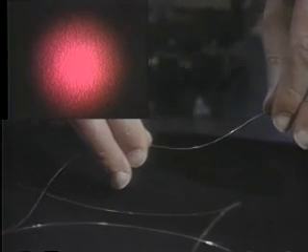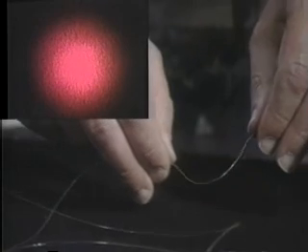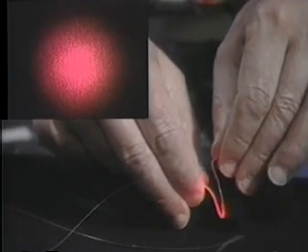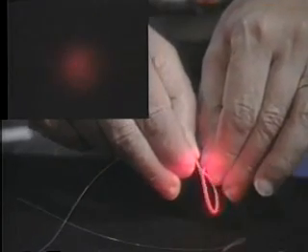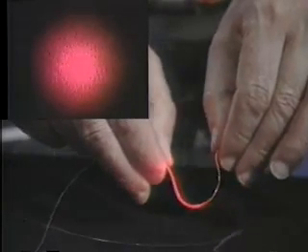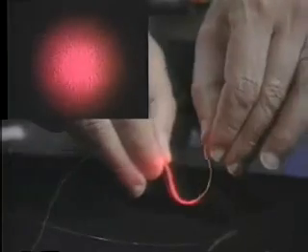So the illustration here shows that if you leave the fiber alone without sharp bends, everything is fine. If you put in a bend, then you can kick out a lot of light, and not much will be transmitted. So you have to be careful. You don't want too tight a bend, otherwise your fiber is brittle and you break the fiber. So you have to be careful how you do this.